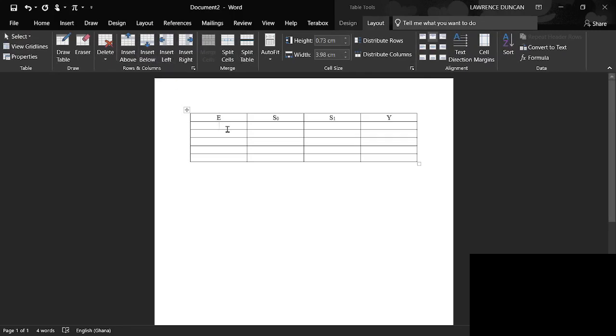So if the enable function, that's my enable indicator, if it's not on, if I have not enabled it, here not being enabled is 0, then all inputted values for any input option, that's either I naught, I1, I2, I3, whatever you input, when your mux hasn't been enabled, it wouldn't work.